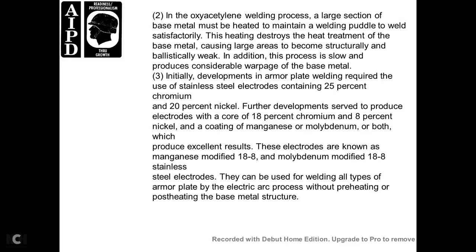2. In the oxyacetylene welding process, a large section of the base metal must be heated to maintain the welding pool satisfactorily. The heating will destroy the heat treatment of the base metal, leaving a large area structurally and ballistically weak. In addition, the process produces considerable warp in the base metal.